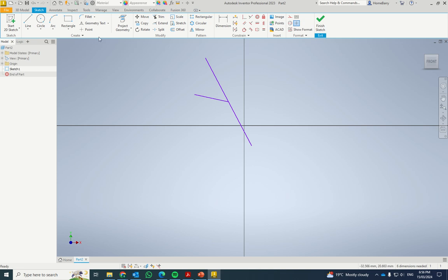I can also use a coincident constraint to say I want this line to be passing through the center point of my sketch. Now I've added another constraint there, and you can see that I can still move this line around. It doesn't even have to touch the center point, but you can see it's remaining in line with that point.